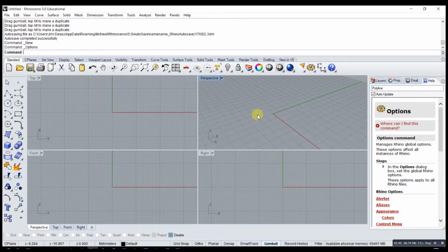So you always want to have your left hand hovering over the keyboard so that you can grab a couple of specific keys to help you move quicker around this 3D space. The Alt key, if you hold down Alt and go right mouse button, that'll allow you to zoom in and out. That's the same function as the middle mouse button or the wheel, and that goes for Control also. If you hold down Control and go right mouse button, you zoom in and out.